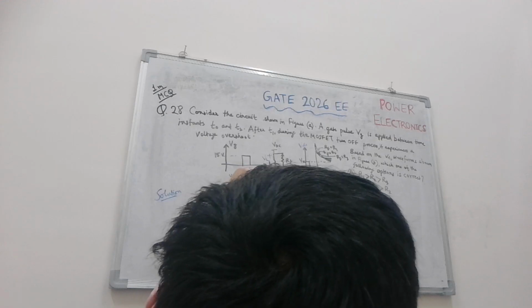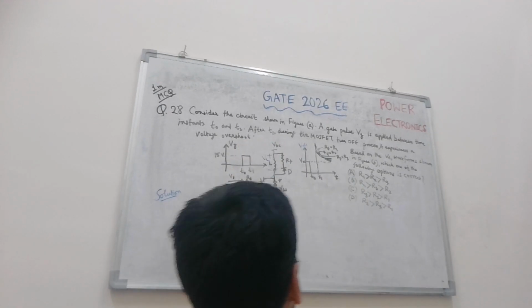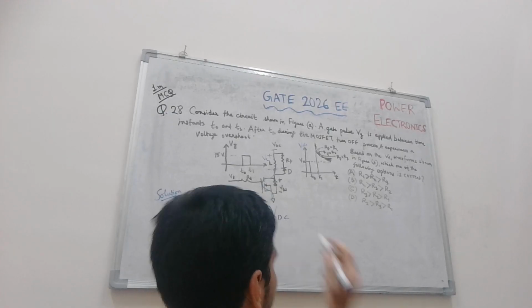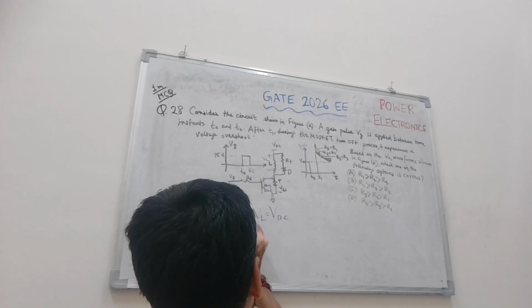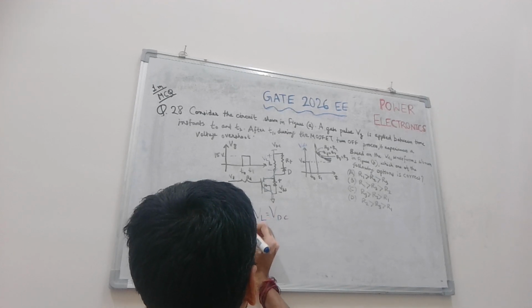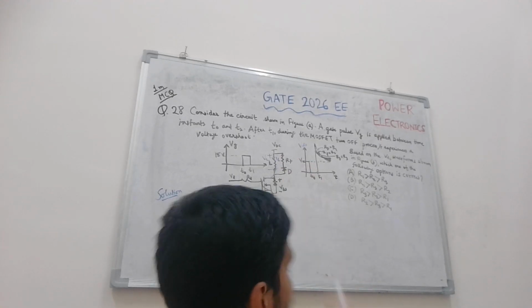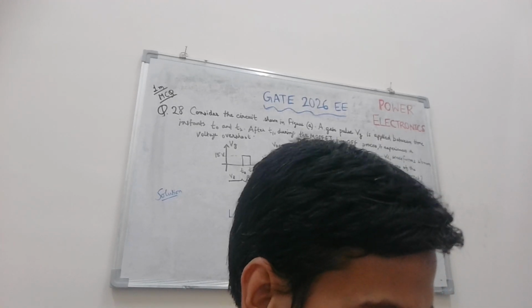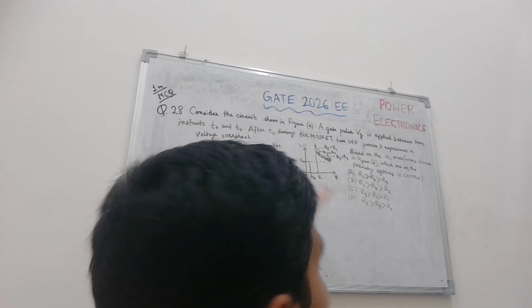This is a short, so this is the ground voltage, so VL equals VDC, and VL is, as we all know, L di/dt. So this is the path followed when the MOSFET is closed between time instants T0 and T1.